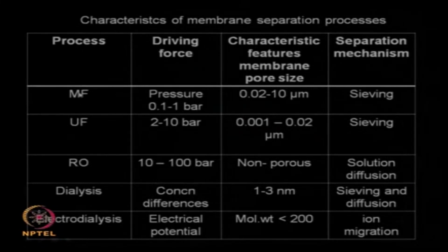If you look at microfiltration, generally the pressure is reasonably low, that means it is operating at either vacuum or near atmospheric pressure, so it can remove large particles, 10 micron particles. So the principle is based on sieving, that means it has a lot of pores, and depending upon the pore size, if the particles are larger than the pore size, they get captured and smaller particles and salts travel through. That is what a microfiltration does.